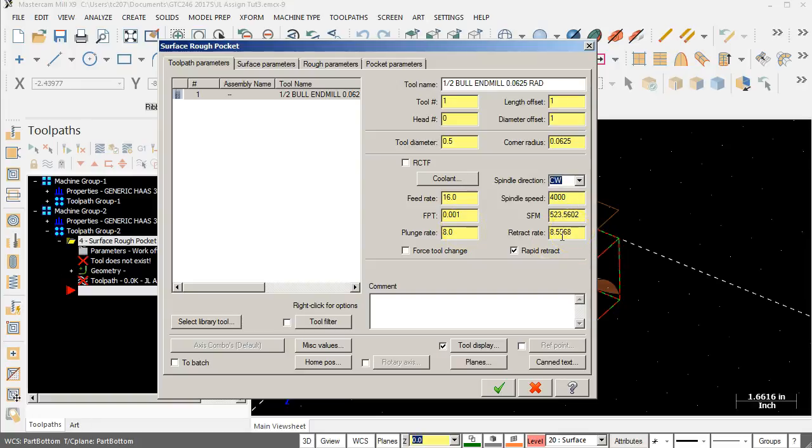So in this case, we're not running production on this. You know, we're going to make one mold or we're going to make one set of molds, but this is not a high production piece. If it were, then we would refine it and go through the steps as we got it out to the machine, saw how it was going to perform. All right, so you know, it's better to be on the low side and run the overrides at the control. Come up with some reasonable numbers for the material.